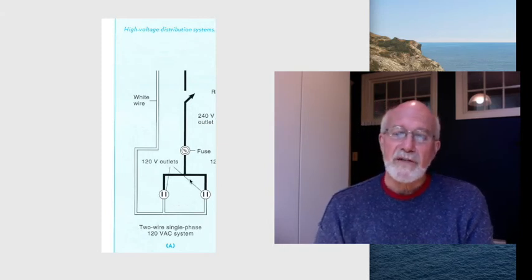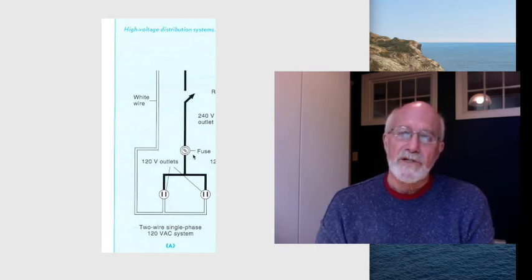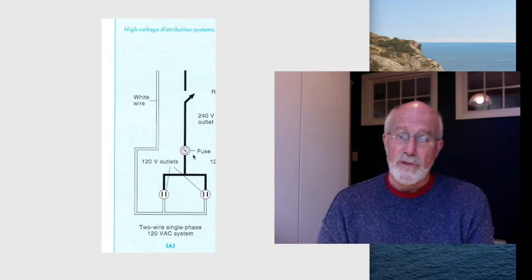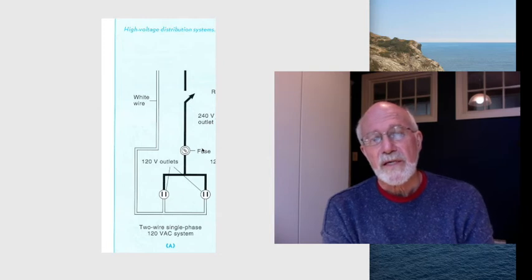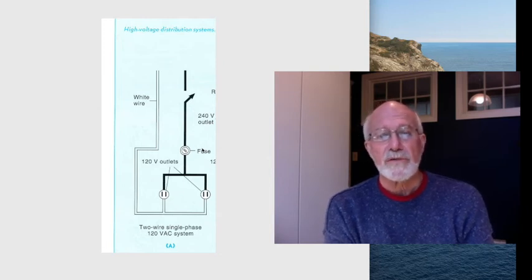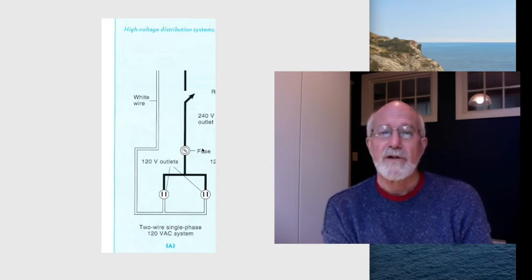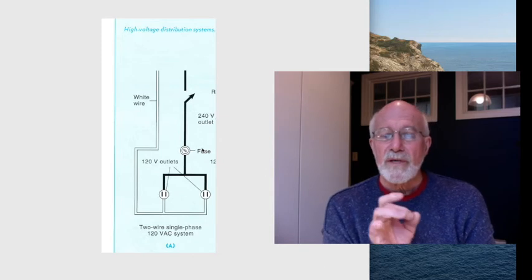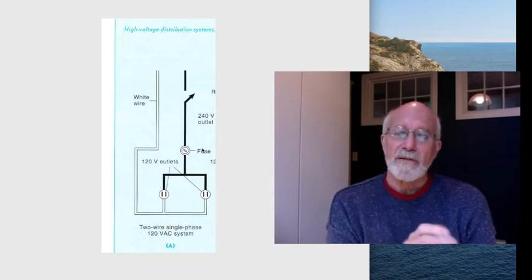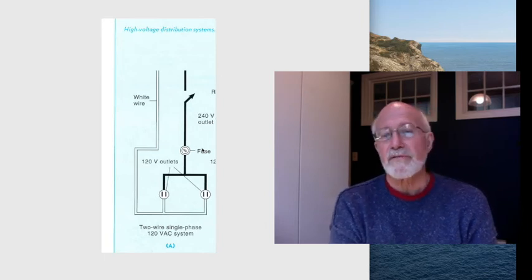It's protected by a fuse. This is old school. Nowadays, it would actually be supplied by a circuit breaker. The circuit breaker or a fuse is simply a component that is designed to switch off or fail when too much current is trying to flow in the circuit, because either something has failed, or the black wire and the white wire in most cases have been joined somehow inadvertently.